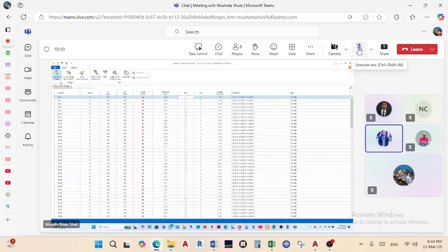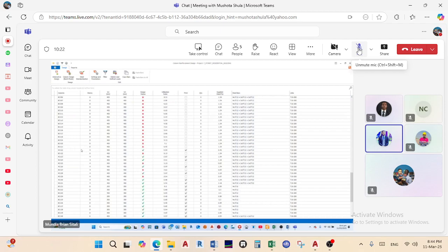From the first class, part of the reason why I had to model the column from the 8th floor and have it run all the way down is so that we could have fewer columns in our building. If we had gone the generate column way, where we model on the 8th floor and then we generate, I think these could be close to 100 columns.